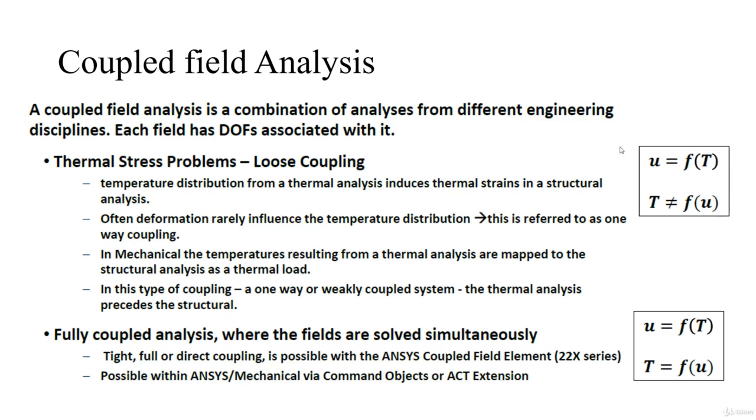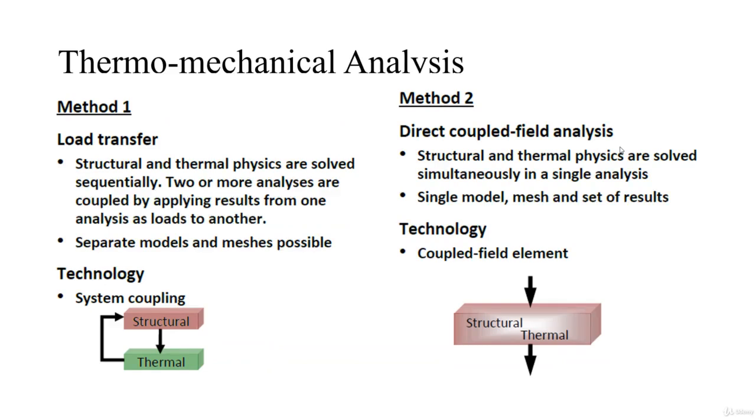Then coming to fully coupled analysis or strong coupling, we have a direct coupling between both of these systems, and if you want to perform this type of strong coupling or fully coupled analysis, you need to have what is known as an ACT system. You need to give commands in the command objects. Then thermomechanical analysis: method 1, load transfer, and method 2, direct coupled field analysis.